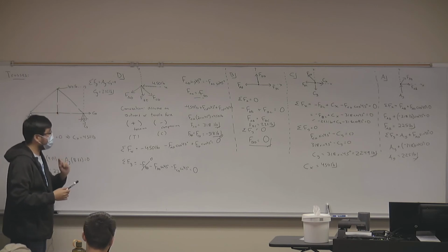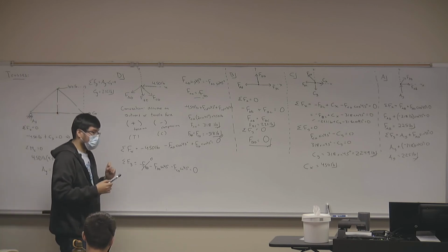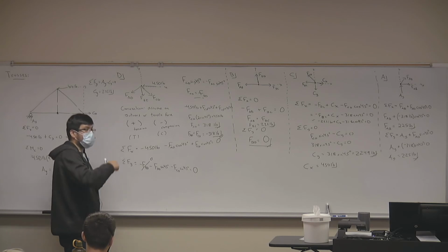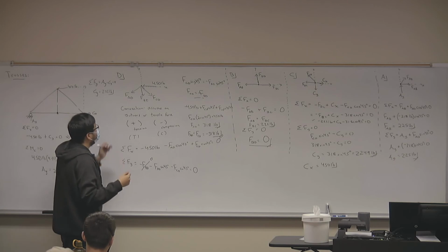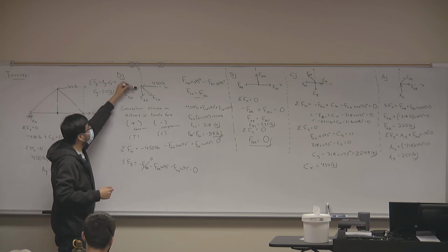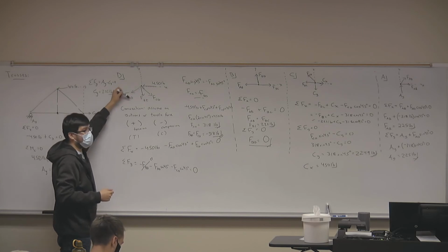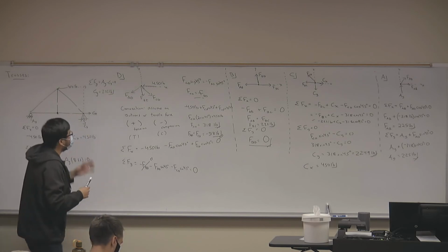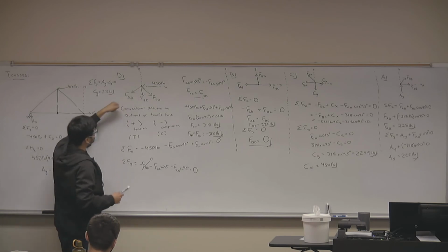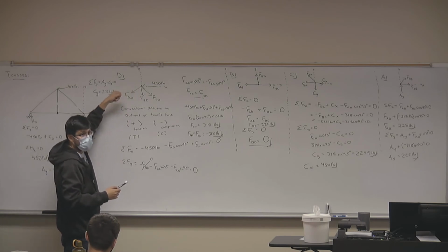So that's one thing. Now, because those are the only two possible forces, we express tension as moving out of your body. So in this case, if this force were really in this direction, moving out of the particle, it's a tensile force. And if it makes you understand a little bit better, I would like to always look at this force and picture myself pulling on this joint, on this truss, right?